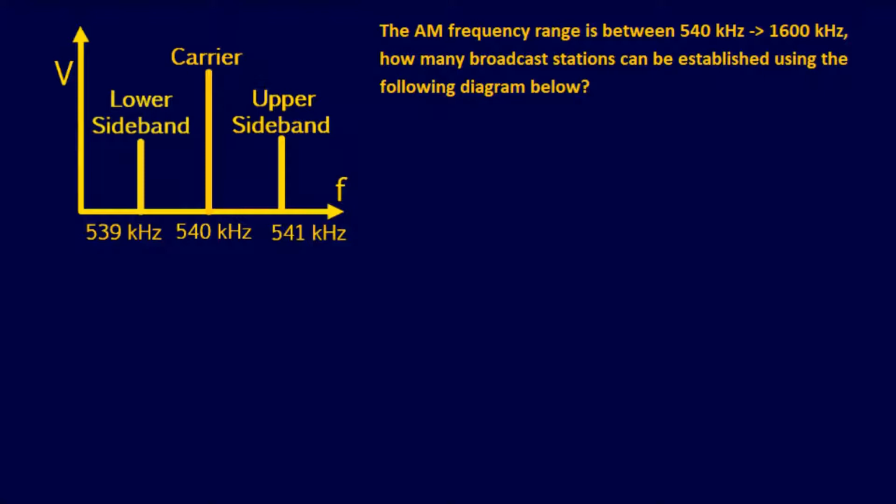Okay, this is where you need to find the bandwidth of each AM broadcast. Over what we know, down here we talked about where the lower sideband is the carrier frequency minus the input frequency. Then this one is obviously the carrier. And this one is the carrier frequency plus the input frequency. All right, so that's pretty simple. Now the total bandwidth for this particular broadcast.